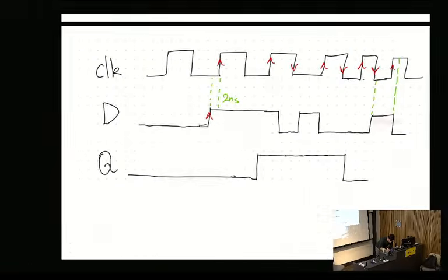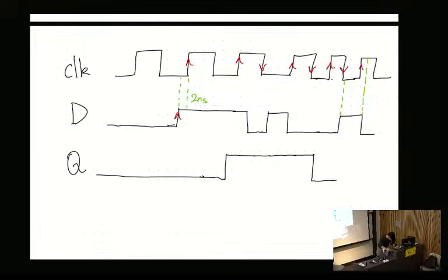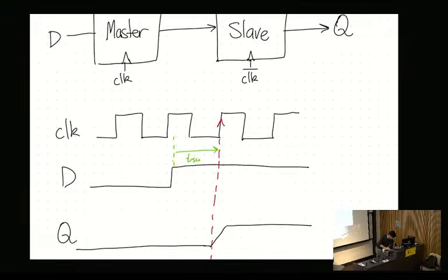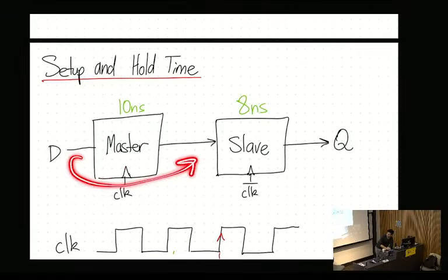So this is the setup time. In this region here, the signal goes high, and we are now in the setup phase because the signal is going high, and the output is different, which is low. So in this portion here, what happens when we get here? Yeah, exactly. As long as this distance is greater than 10 nanoseconds, let's just say it is, we don't have any setup time violation. That means the signal has successfully gone from here to here. That's great.